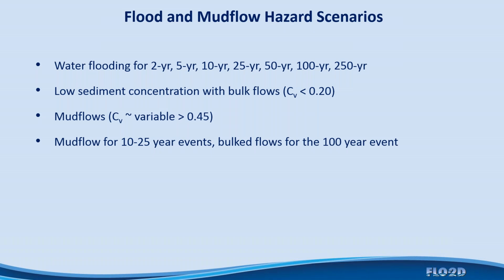So now when you want to do your project, whether that's a mitigation project, a replication project, or a hazard project, you're going to come up with some different scenarios. And maybe you have developed a hydrograph for the 2-year, 5-year, 10-year, 25-year, and so forth events. And also maybe you have a historical event that occurred last year. And so you might have some estimates of the hydrology. You might have the rainfall amount.